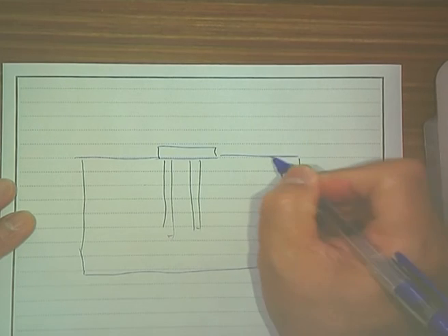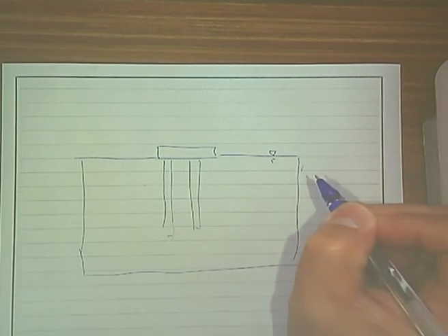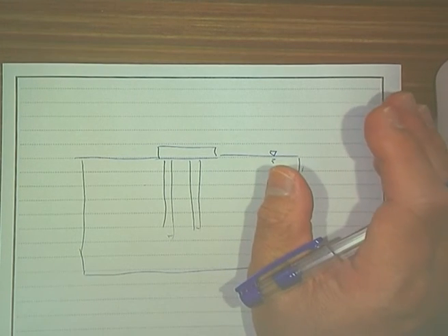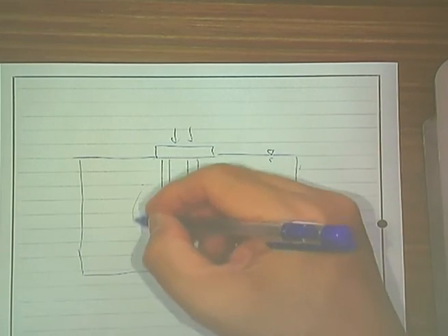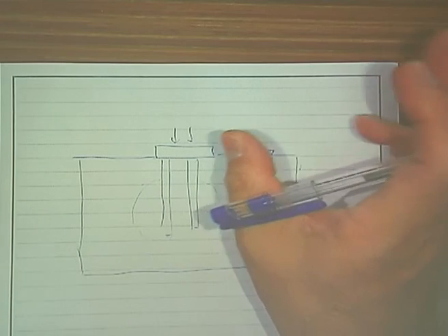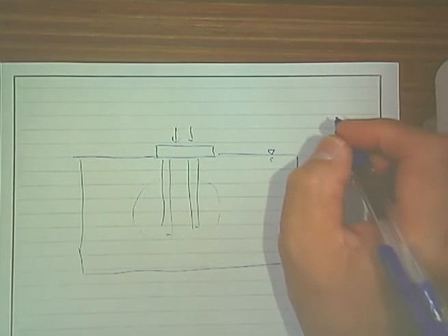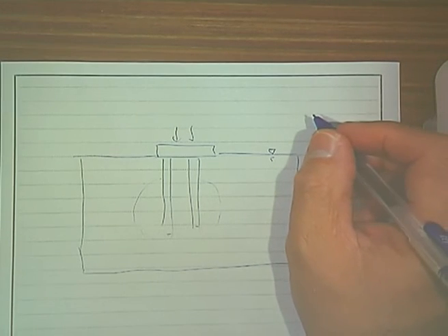Just to simplify things, let us assume that the water table is always at the ground surface. Now, when you start loading up the pile, obviously in the short term there will be some excess pore pressure around the pile, and the excess pore pressure will start to dissipate outwards. Assuming that you don't change the groundwater table, this is a very simple situation.